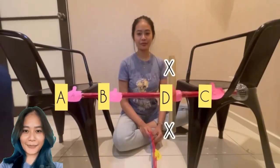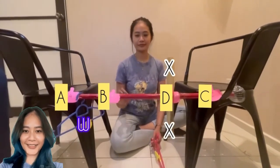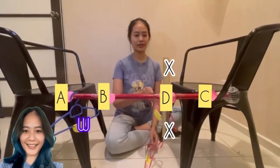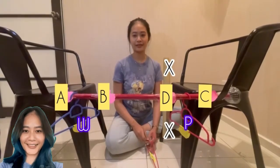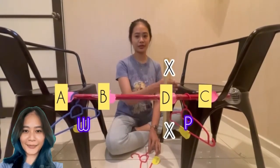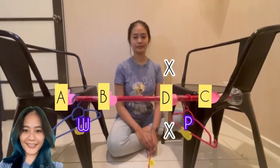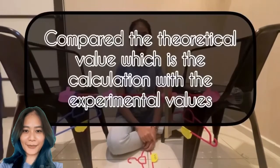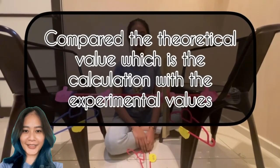First step is to put the load W at point A. Then we put load P between points C and D. Next, we measure the distance from point C to the load, and then we will get the bending moment at section XX, which is at point D. Lastly, we compare the theoretical value, which is the calculation, with the experimental values.